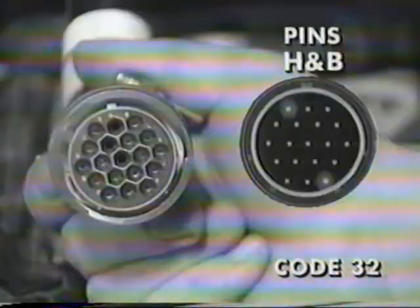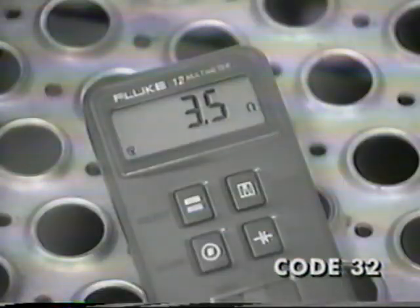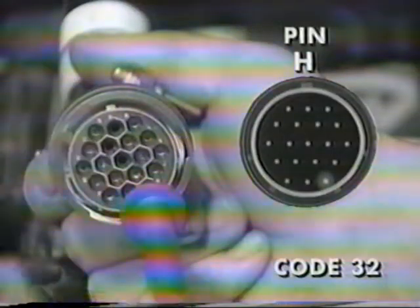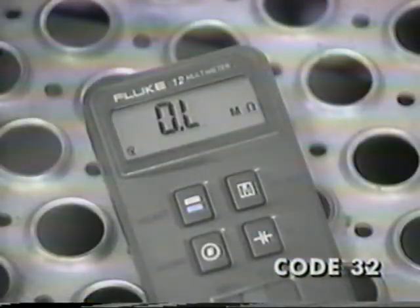If the readings are okay, reconnect the harness to the solenoid, then disconnect the vehicle interface harness at the shift bar cover. Measure resistance between pins H and B. Again, you should get the same readings that you got across the solenoid connector. Now, measure between H and ground, and you should get an open or infinity. If the readings are bad, the vehicle interface harness is bad. Repair or replace it as necessary. If the readings are okay, then the problem is with the shift bar cover.